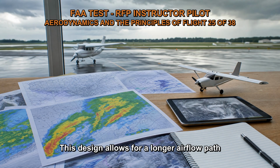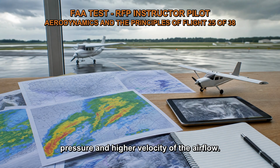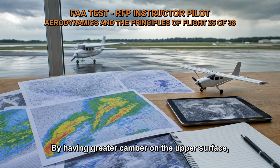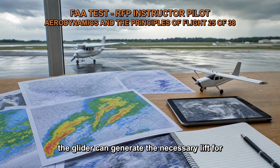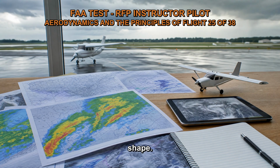This design allows for a longer airflow path over the curved upper surface, resulting in lower pressure and higher velocity of the airflow. According to Bernoulli's principle, this pressure difference generates lift. By having greater camber on the upper surface, the glider can generate the necessary lift for flight while maintaining a streamlined and efficient airfoil shape.